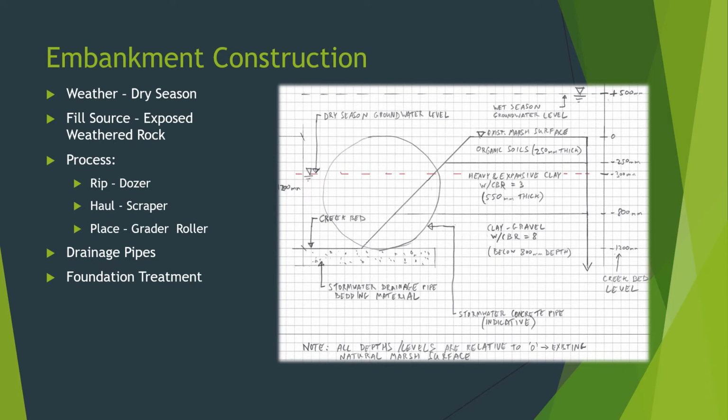So moving on to the second element for discussion of this report, which is embankment construction. As previously stated, the embankment should only really be constructed in the dry season, otherwise it presents significant issues with stormwater runoff and also between subsurface and surface flows.